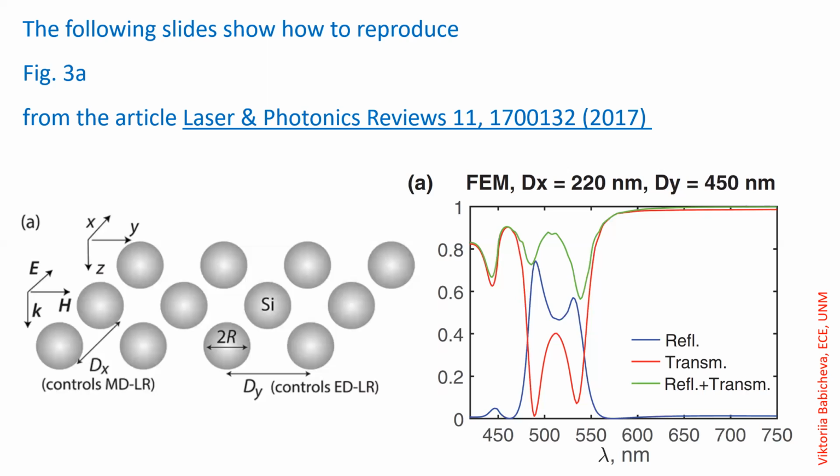The main emphasis of this tutorial is on how we set up a simulation domain using variables. I will show the procedure of setting up the variables for a number of simulation characteristics of the domain, including dimensions of the object, excitation source, mesh, and field monitors. I will show step by step how we write a script for each of these structural elements.